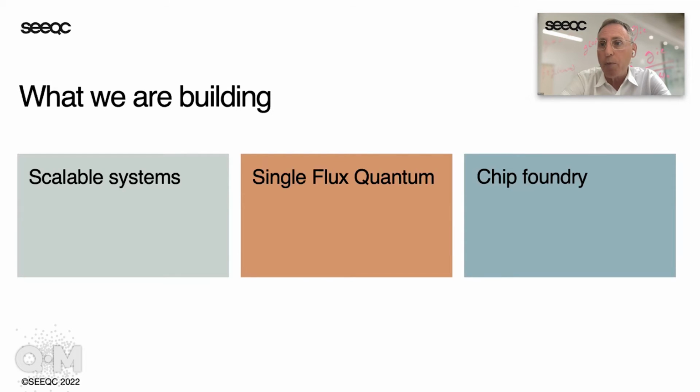And so our systems operate typically between 30 and 40 gigahertz. We've built classical logic operating at 750 gigahertz, the fastest digital logic in the world. We operate at 3 to 5 orders of magnitude lower power, and we operate at a nearly zero noise floor. We do that in a chip foundry, not unlike Rigetti, although our chip foundry is for more classical electronics, but again, these are all single flux quantum as opposed to CMOS, so we see those advantages.